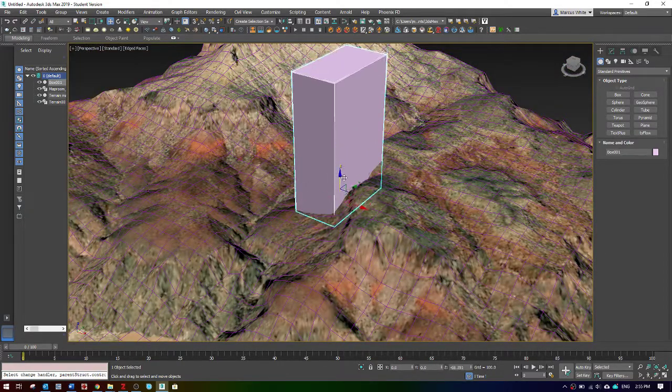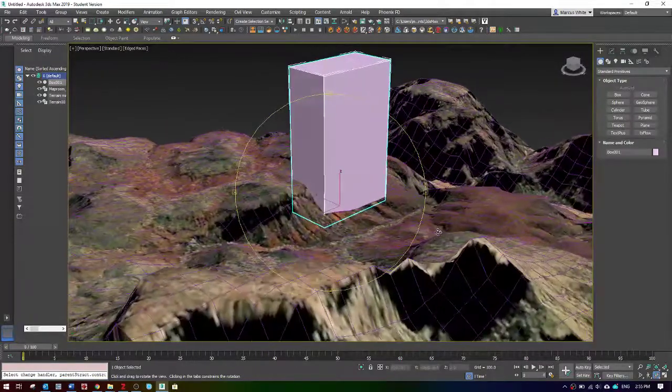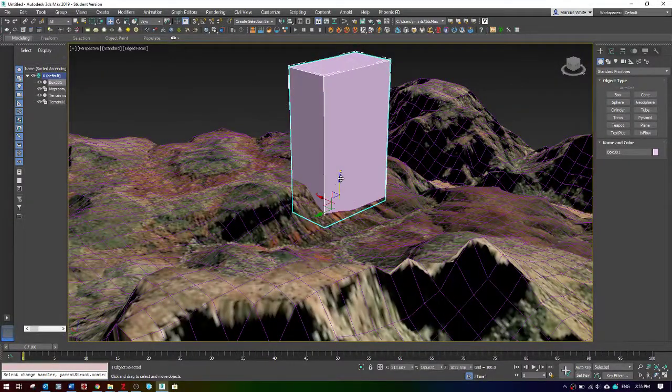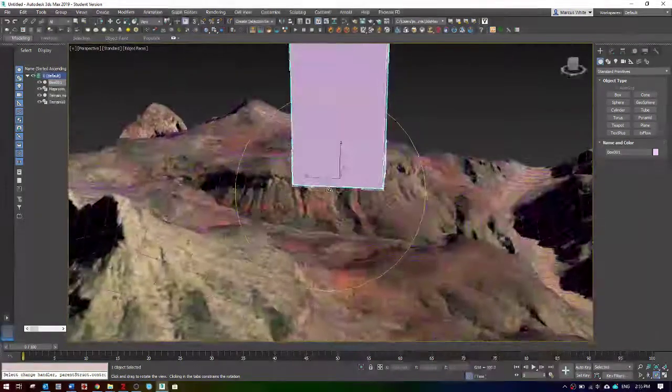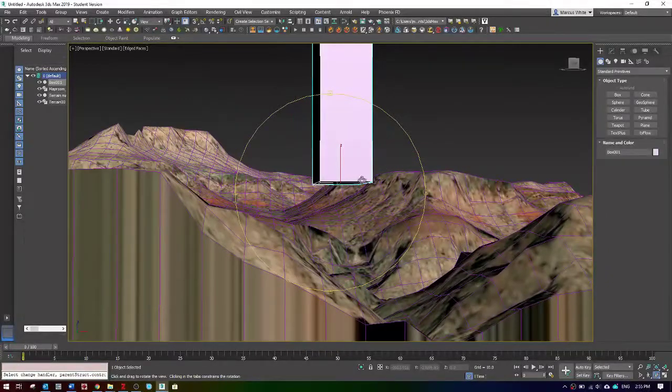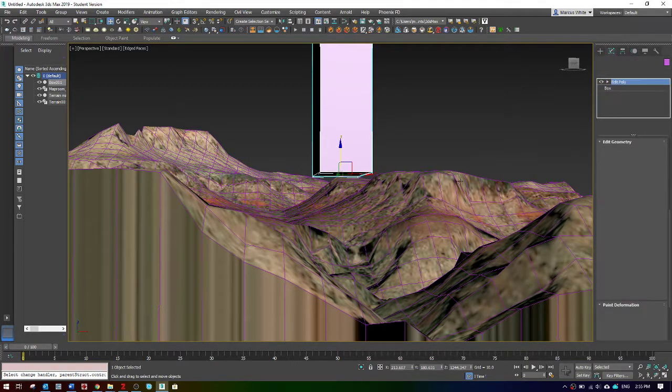If you're using Maproom, you can play with the settings to get this pretty close, but sometimes Maproom will get a bit confused as to where the bottom of a building is, so it might be setting something like that. That's not going to print super well, in that it's not overlapping enough, so you might just grab that and drag it down, or you could do an edit poly,